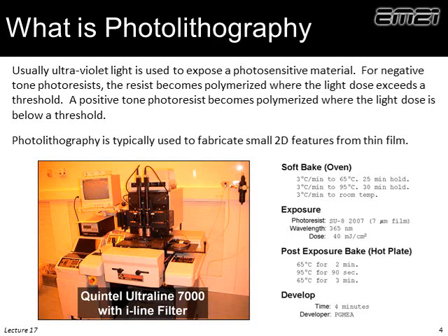Positive resist acts the other way. Wherever the light is exposed, that's where it does not harden, and we can wash that away in a developer solution. So using this, we can make structures with really, really fine features.